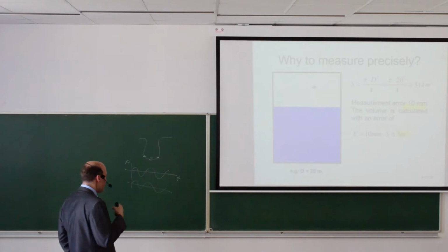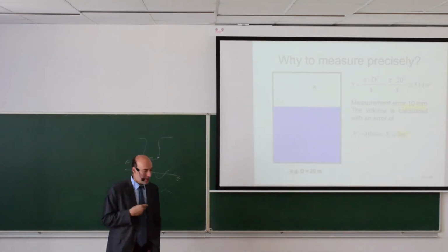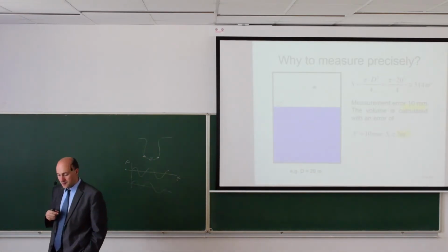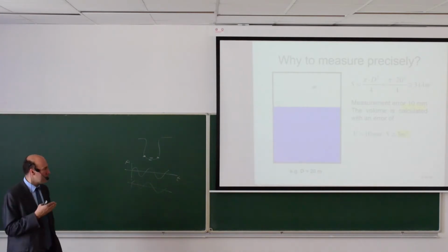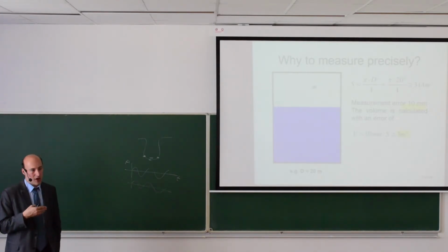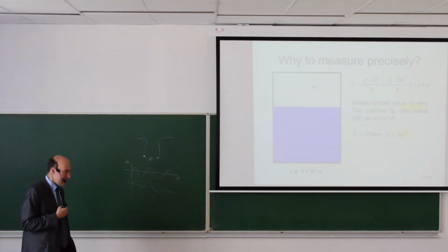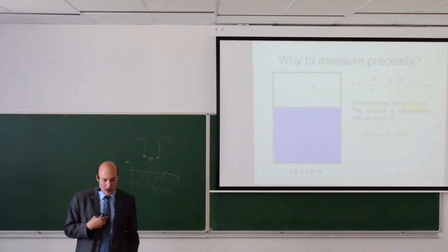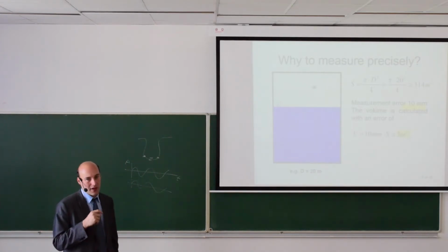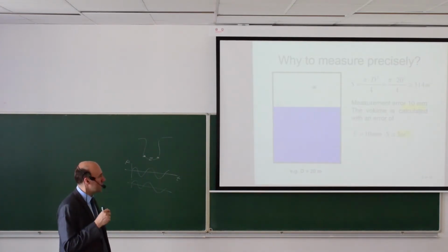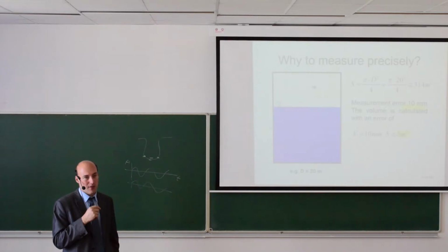So liquid level sensing requires typically a very high accuracy. If you are talking today about radar sensors, which are the most accurate ones, then the requirement is usually sub-millimeter accuracy. So you have resolution that is better than 1 millimeter.